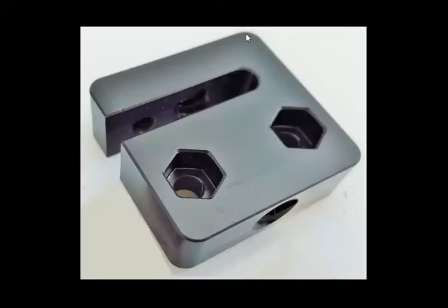What we're going to be doing here is we're going to establish the part size. We're going to use that with the part size wizard. We're going to cut this slot using the oblong shape in the Shapes Plus wizard, hex, and the hole for the bolt. There's nuts that get pressed into this hole. We're just going to be doing the top view, so all you see will be the slot and the holes and the shape of the outside.